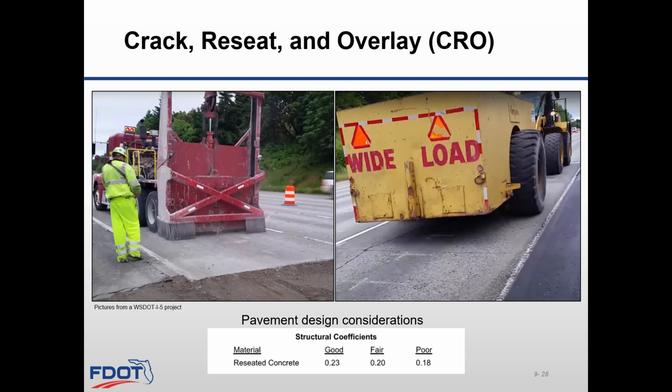Design details need to be provided for areas where there is a transition into a bridge approach slab. An appropriate thickness transition length should be provided for high-speed facilities. Another area where design details would need to be provided would be an area of a bridge underpass.